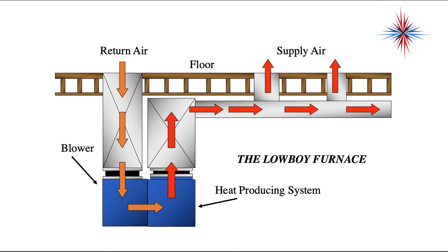Now, the one thing I want you to note is in all of these configurations that we've talked about, the fan is on the cold side of the system. So we don't suck air through the heat exchanger. We always blow air through the heat exchanger. We're going to talk more about this, but the return side of the system is always what we consider the negative side. It's a low pressure. The supply side of the system, the heat exchanger side of the system, is what we call the positive side of the system. It's higher pressure than the surrounding air.